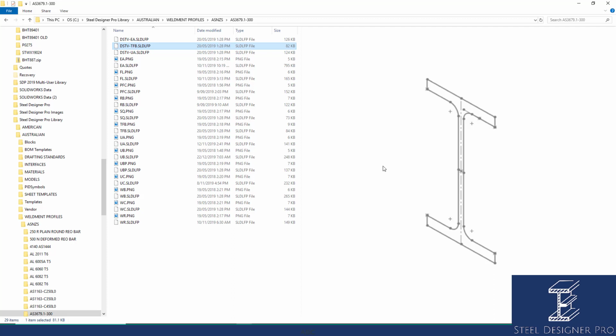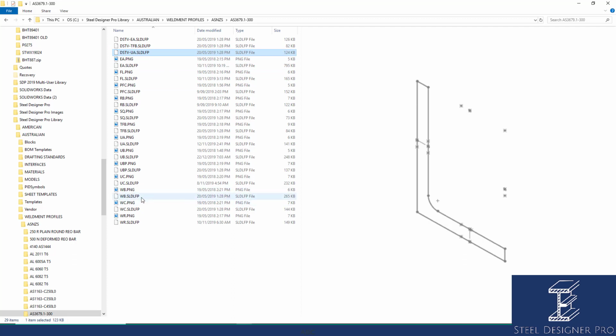That's just a first step, something that you need to look at. All we did was we just grabbed the weldment profile and copied it and put DSTV in front of it, and then we went in and we just removed any parallel processes or removed any of the curved surfaces out of there so that we can get straight edges.